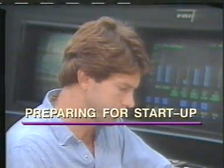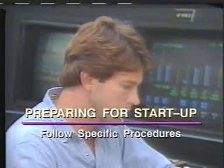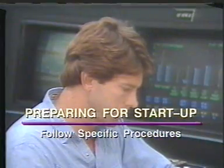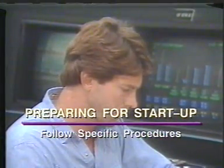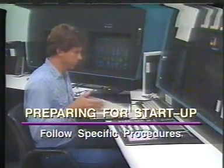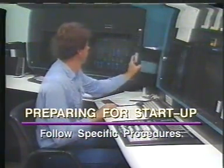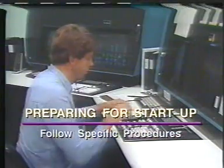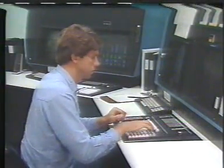The procedures for the actual tower startup will vary from column to column. You should always follow the guidelines for your particular tower. Remember to make gradual increases in temperature and pressure when starting up a column. Rapid temperature and pressure changes can stress and damage equipment.